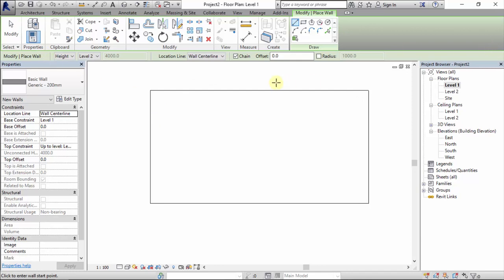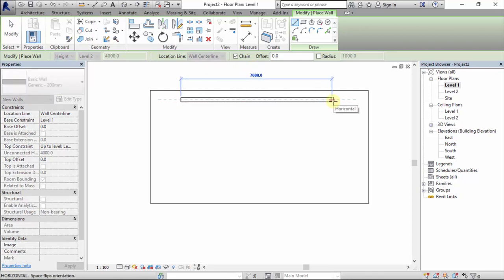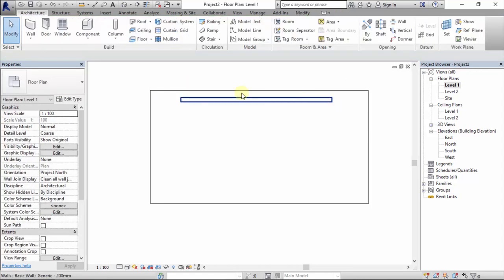I'll be showing you everything on the options bar and what each of them actually does. And the first feature we see here is the height or the depth drop down. If you click on the height drop down as it is, if I draw a wall, it goes from the current level to the next level, basically like stacking up blocks to rise from bottom to top.